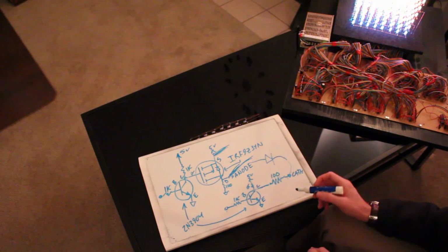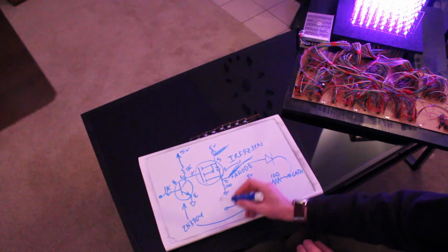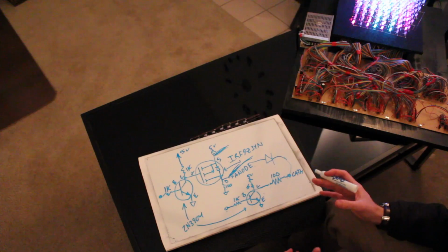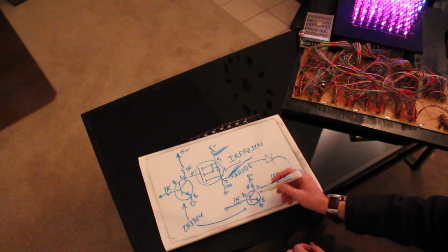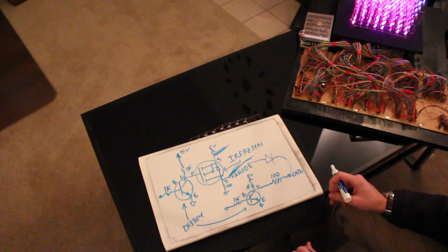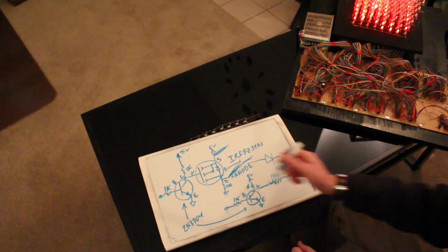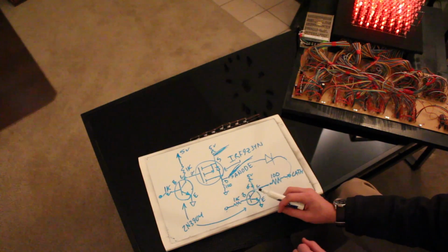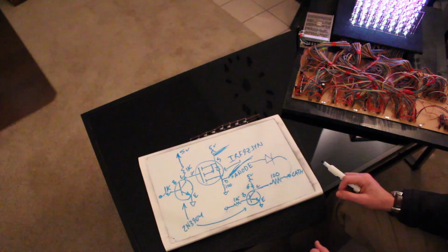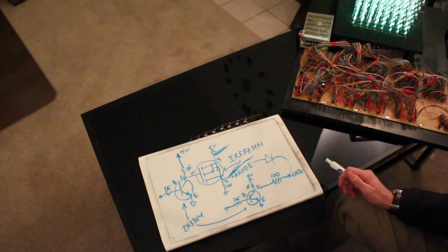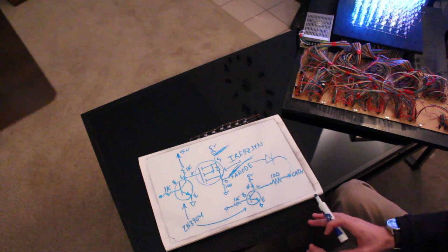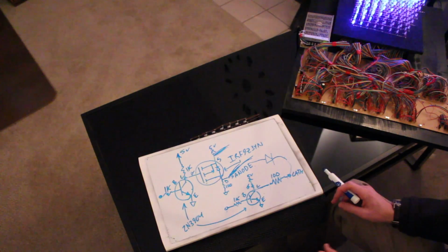Okay, so you sort of add all this up, meaning I have 192 of this circuit. So I think in my demo video, I give you a total count of the transistors. There's 192 for the cathode, and then there's 8 for the anode, giving you 200 NPN transistors. And then you could add up all the 1Ks, 2 for the 192, and then plus the 2 for the 8. You sort of add all that up, and you get over 400 or something crazy. So that's pretty much the entire hardware circuitry. You just have to imagine this being repeated a ton of times.